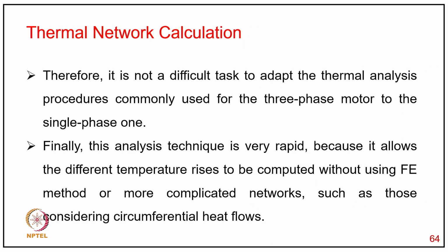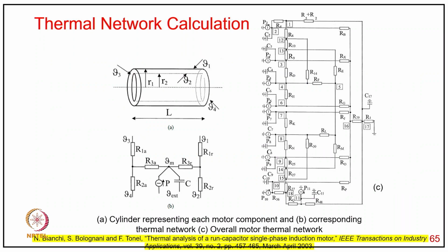Therefore, it is not a difficult task to adapt the thermal analysis procedures commonly used for three-phase motors to the single-phase one. And finally, this analysis technique is very rapid because it allows the different temperature ranges to be computed without using finite element runs or more complicated networks, such as those considering circumferential heat flows. A typical example is a thermal network, with cylinders representing each motor component, and the overall motor thermal network.